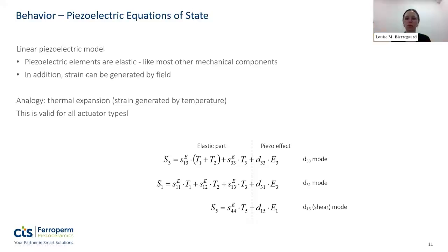Sorry. Charles, you got a question also from earlier. It asks: what about harsh environments like the greasy automotive industry? So I think it was about one of the previous slides. Well, the piezo can take some harsh environment, but it's somewhat limited, right? Because we have a device that is subjected to an electrical field, so there is voltage applied. You want to avoid any electrochemical reaction. So it depends really what environment we're talking about.